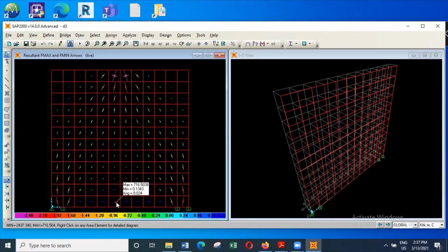And because there are inclined forces of compression nature, we have to provide tension reinforcement at the bottom. So here we say, we are actually looking at a strut and tie method. So these are the struts, and this becomes the tie.